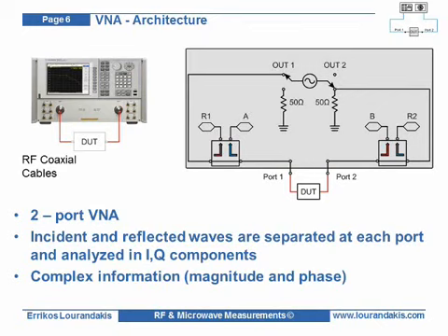In the forward direction, the internal source is switched to analyzer port 1, while port 2 is terminated with 50 ohms. The incident wave is passed through the bidirectional coupler to port 1 and detected at reference receiver R1. The portion of the incident wave that is reflected from the DUT is passed through the bidirectional coupler to receiver A. Now, from the ratio of reflected to incident wave, the reflection parameter S11 is calculated.